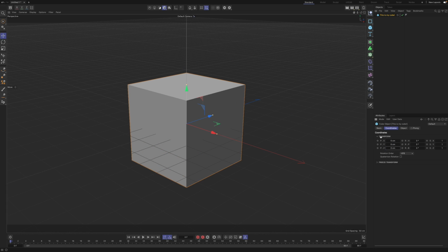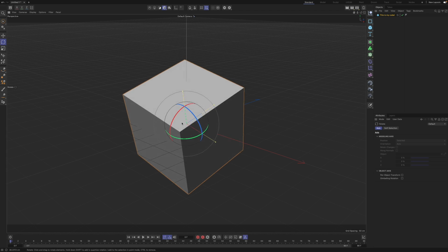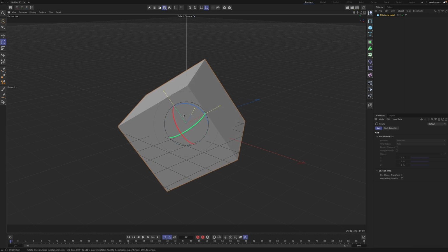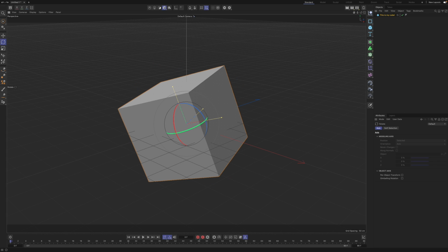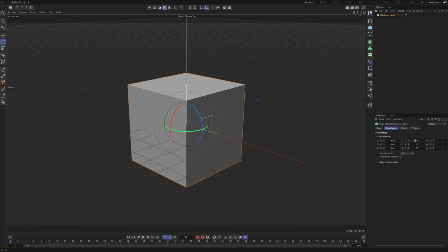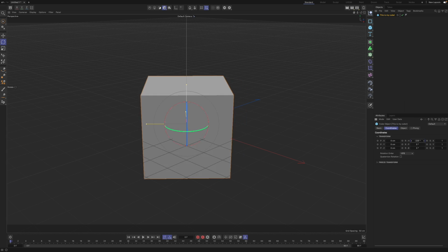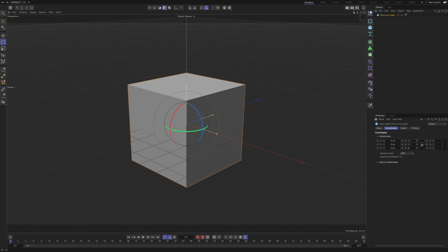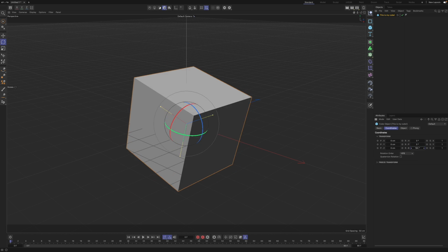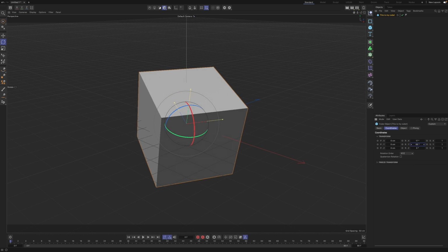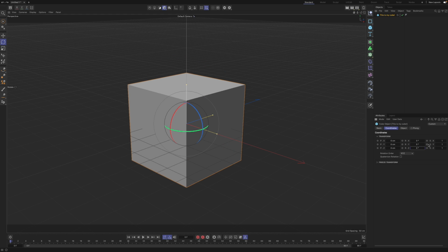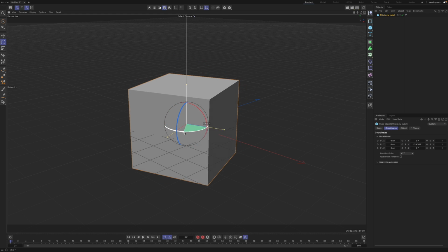and I can reset these all to 0. I can hit R and we can rotate, and so you can see me just grabbing it, not really grabbing any of the axis rotation specifically. I can just grab full control. I'm just going to undo that, but if I click here, you can also drag or type in numbers. You can see this rotates along the y-axis, the x-axis, and the z-axis. You can just change that to however you see fit. I'll change it to XYZ, so you can see that, and that. So I'll reset to 0, and obviously you can always just turn it.